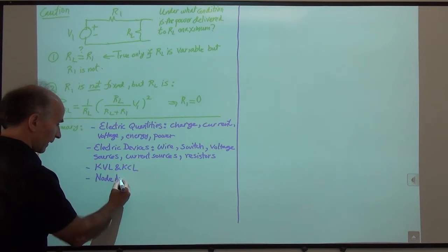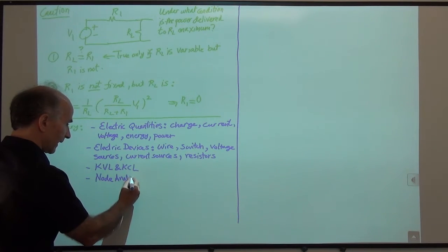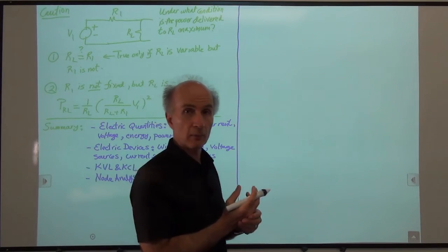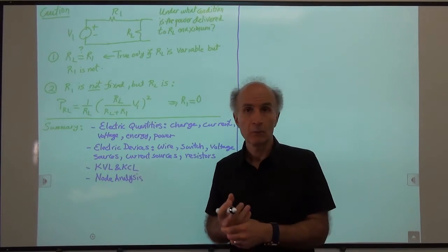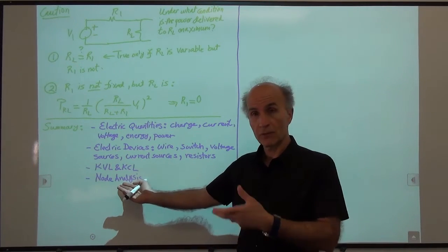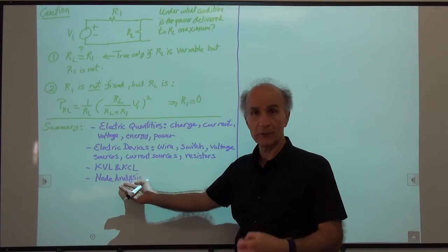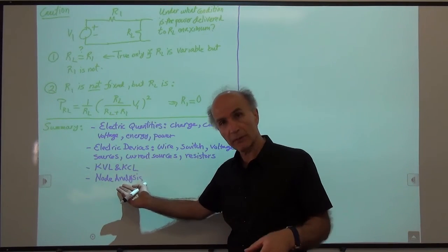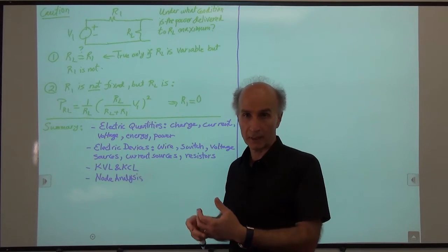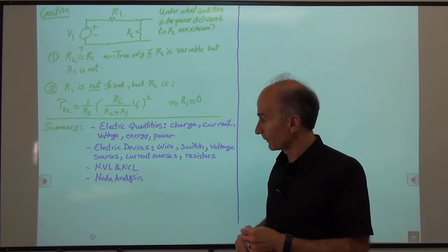We saw that node analysis is a KCL-centric process. We're going to write some KCLs at the end. And when we solve those KCLs, we find a bunch of voltages. So we assign some voltages to the nodes after we picked our ground. We found the currents through the different branches. We wrote KCLs at those nodes. We solved n-1 equations and got n-1 voltages.